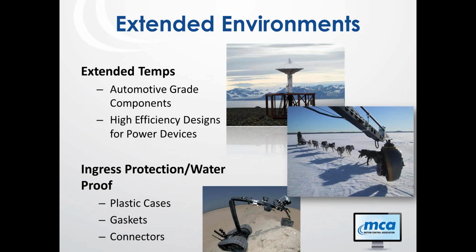Extended temp, this is by far the most requested feature that we see here at Advanced Motion Controls and that I hear in our applications group: how do we deal with these temperature extremes? And we do that by using automotive grade components. And we also deal with high efficiency designs for power devices. Also, how do we keep the system intact? How do you keep dust or water out? And we do that with plastic cases, gaskets, and connectors.